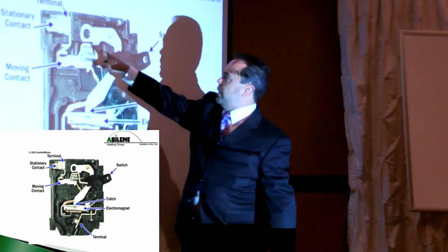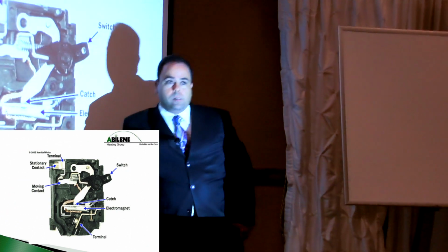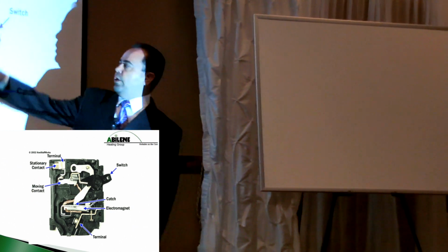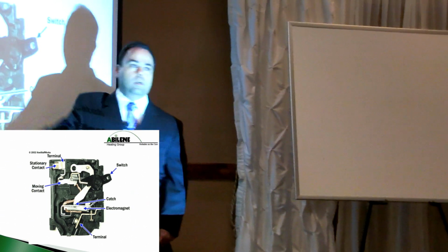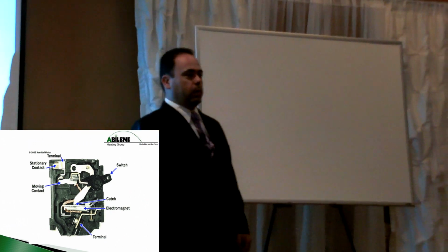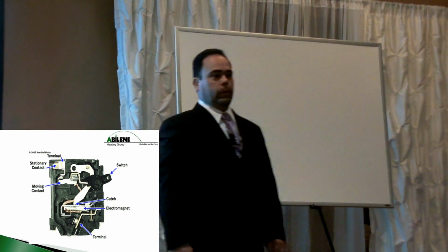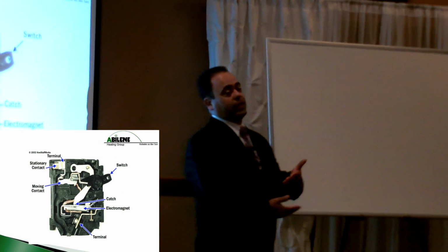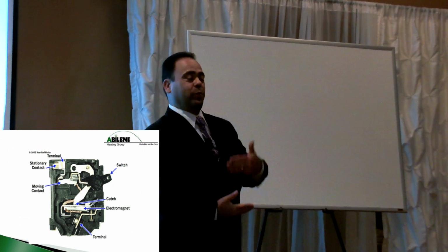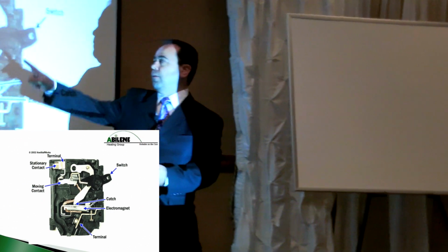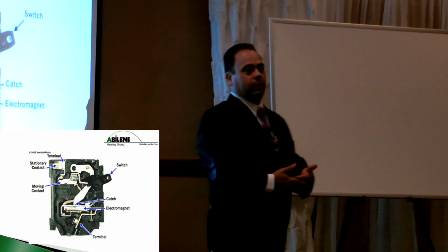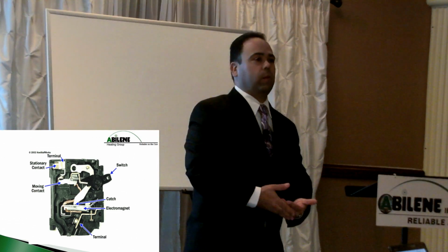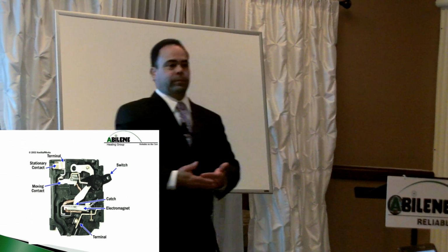This is a closed circuit coming through and feeding the panel, feeding the wire. When this trips out, this opens right here. It's an open circuit. Kills the power downstream. All right, so all it is, is a protective device. Very important that it's sized properly. Because if we don't size it properly, the chances of that tripping are less. And if it doesn't trip and there's a problem, what happens? It could burn.